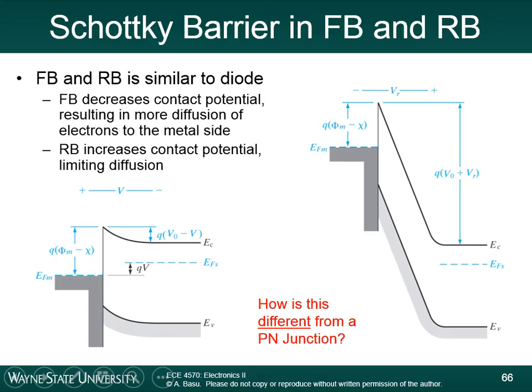Can it go in the opposite direction? I heard yes and no. Oh, I'm talking about the forward bias right now. So in the forward bias, we've reduced this barrier height so the electron says, oh, hey, I see an empty state near me, and it's way down here in energy. I would prefer to go to the lower energy state. So the electron will just hop down here. That's how you get conduction in the forward bias.